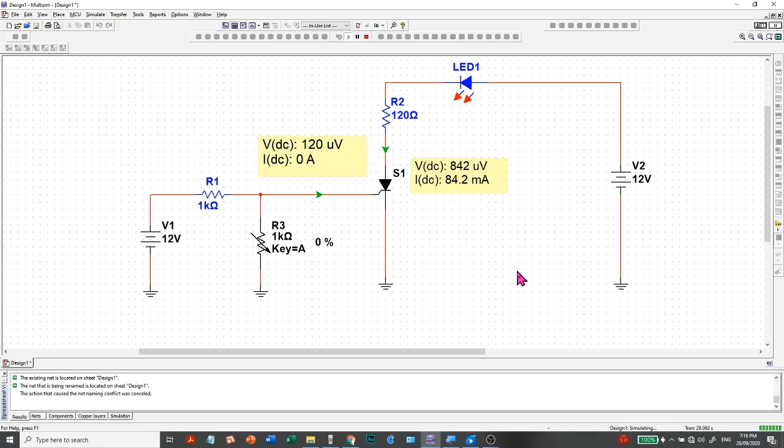First method is anode current interruption. That would mean we remove the current flowing through our anode, and we also have forced commutation. So I think the easier to show here is our anode current interruption, so we'll do that in this example. In order to do anode current interruption, we would want to either cut off the current flowing through the anode, or divert that current in order for it not to flow on the anode.